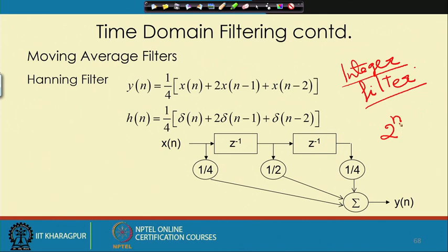As we have the binary representation of the data, we can do the scaling by shifting the bits in the register. So, if we have to divide by 4, which can be represented by 2 to the power minus 2, what can we simply do? We can do a 2 right shift, and that gives the scaling.